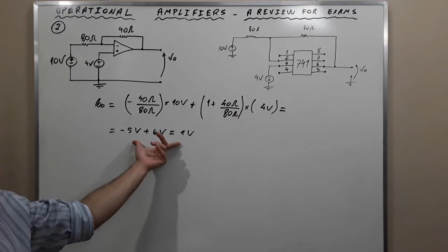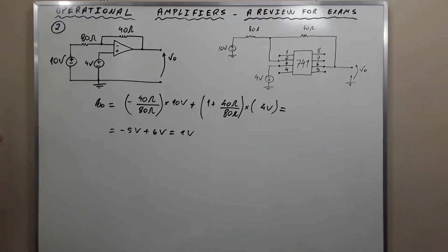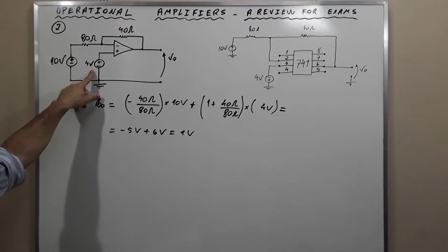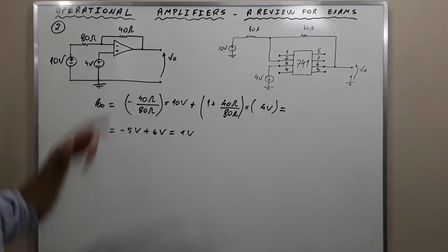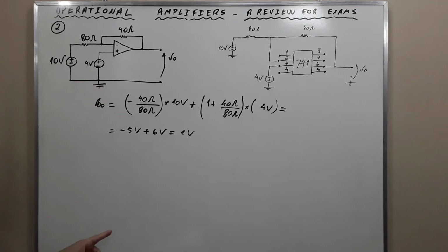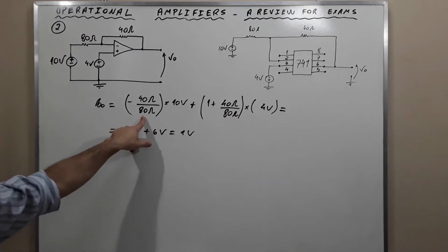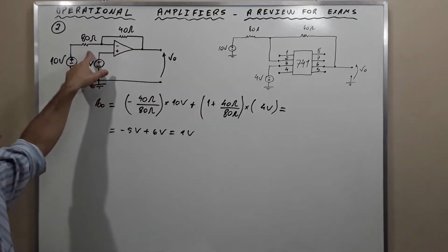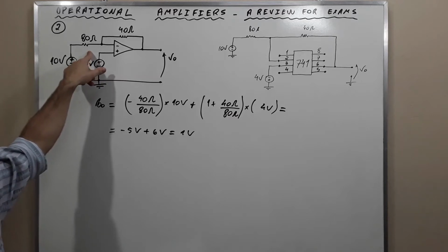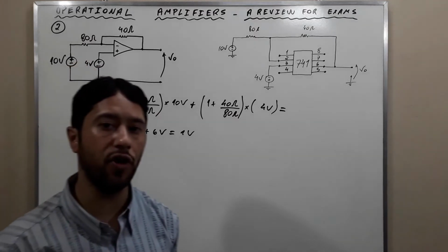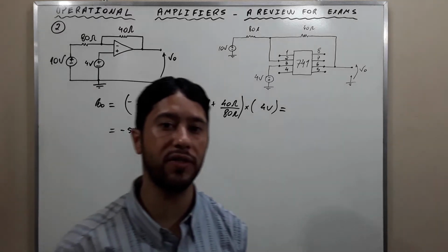Then we are implementing a difference amplifier, but if we change the polarity here, instead of the difference, we are going to have the addition, okay? The addition, and this addition is going to be amplified according to the values of the resistors that make the feedback loop around the operational amplifier. Okay, my friends, and this is all for exercise 2. Let's go to exercise 3 now.